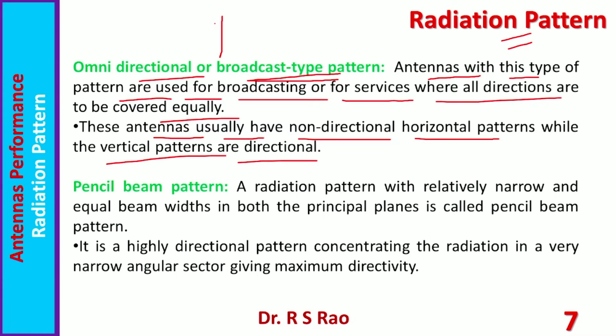When it is excited, the half-wave dipole radiates equally in the horizontal plane, equally well in all directions in the horizontal plane, omnidirectional. Of course, this equality, sameness, is only in the horizontal plane. When we consider a vertical plane, the pattern is like this, dumbbell shape.